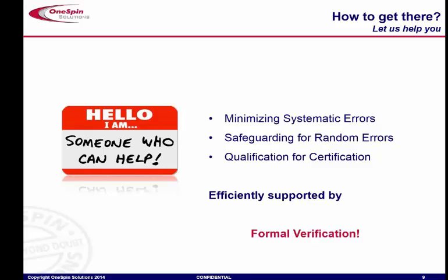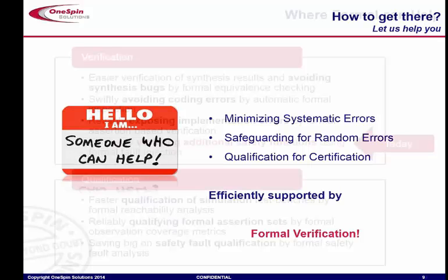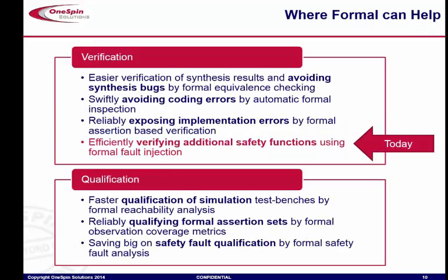Formal can be applied in quite a lot of scenarios that are required. Namely, you can look at the traditional equivalence checking, just making sure that your synthesis doesn't introduce anything or doesn't optimize away any of the safety functionality that you have put in.